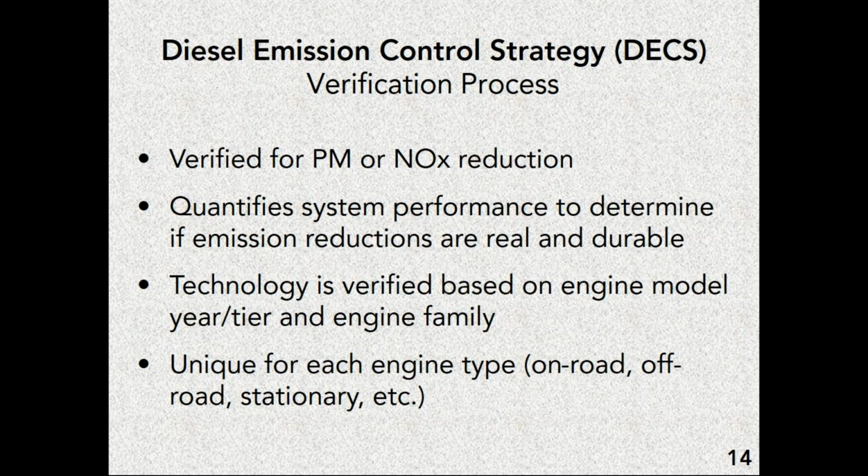It puts them in a class where they technically have proven that they meet the emission reduction requirements that are required by law. Now, this quantifies the system's performance. We verify these systems for particulate matter and NOx reduction. It's verified based on what engines and tiers of engines that it can go on, and it's unique for each engine type.